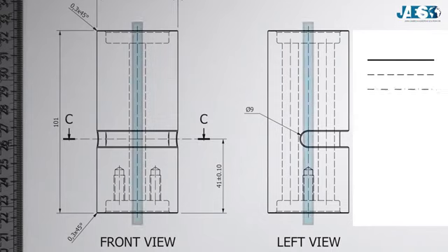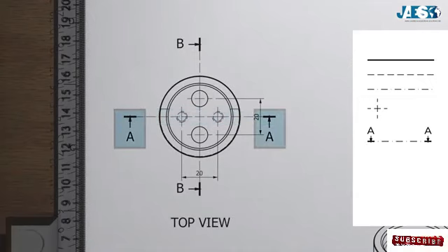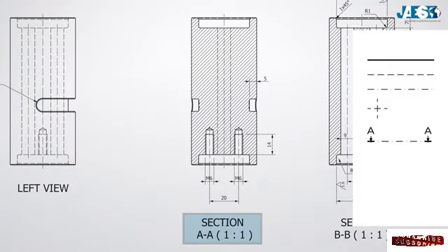A dashed dot line, on the other hand, indicates symmetry if the object on either side of the line is substantially mirrored. They are also used for holes. A dashed dot line may also indicate a section if there are arrows indicating the direction of the view and letters that are shown in the actual section drawing.